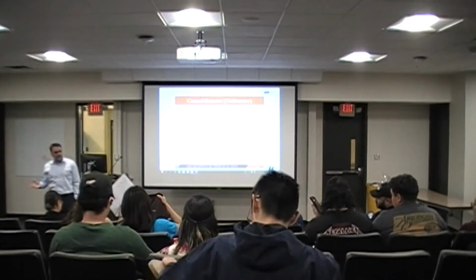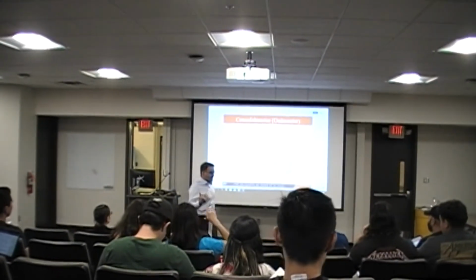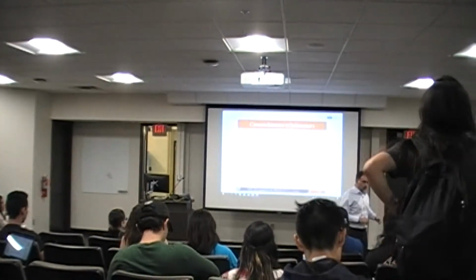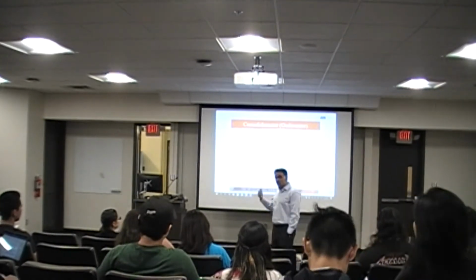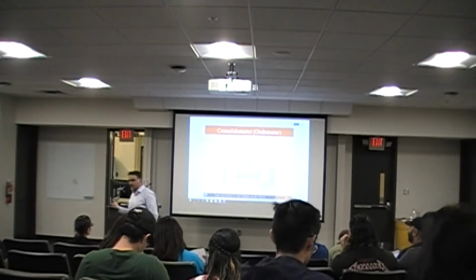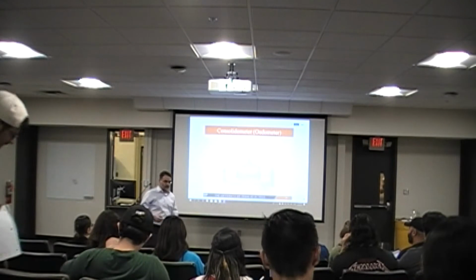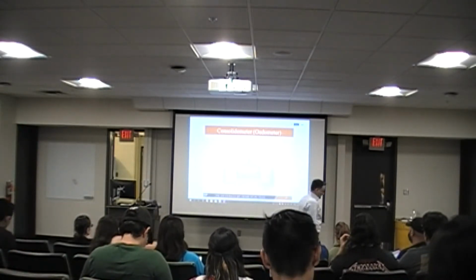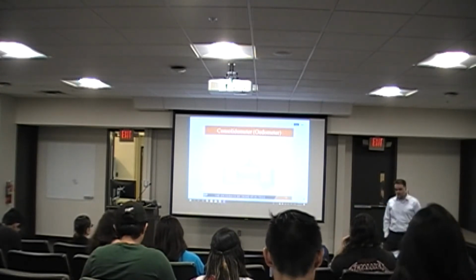On the other side, you had the information about the stresses exerted by the weight of the structures, right? Remember, for instance, based on the information that you had from your LRFD or the ACI method, you had a U value, which was the weighted loads, right? Remember, you had the dead load, you had the live load, you had different coefficients that you can basically use to inflate the magnitude of the load to be able to account for the uncertainties in the loading conditions.